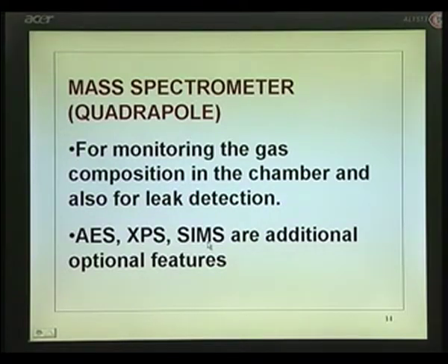These are the benefits that you get when you use the MBE system. Because of that, you can get high quality layers, because you can ensure that the contaminants are not there, and you can ensure that the growing layer is perfect. In situ you can examine. You do not have to take it out and say, let me see what I have got. You see it right there.